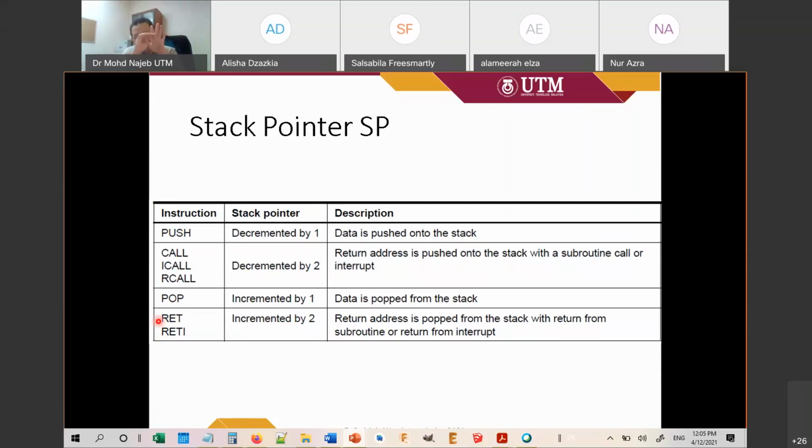And then when you continue your main program, you can continue your process and you can continue to use your R1 to R32 with the values inside them like normal, like nothing has happened. But you need to do all this process. You need to use the stack pointer, you need to push, then you need to pop, and then you need